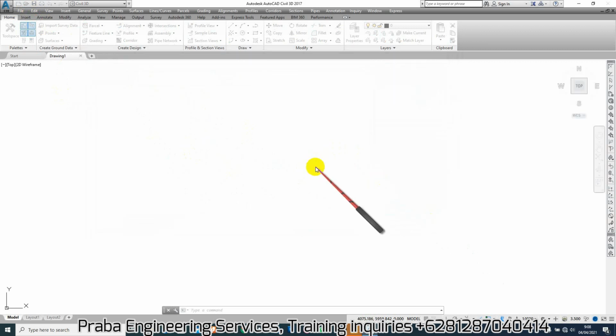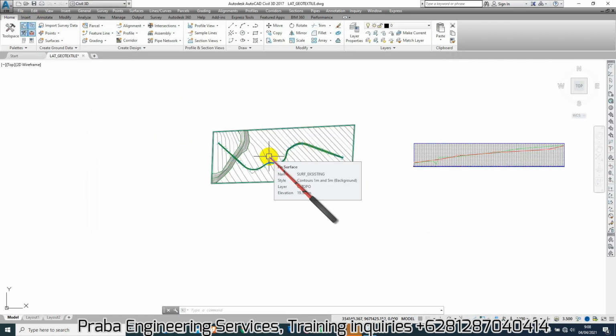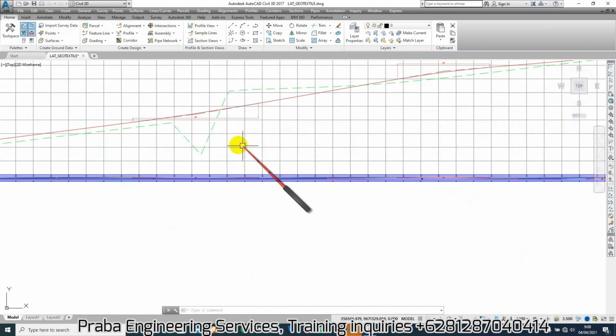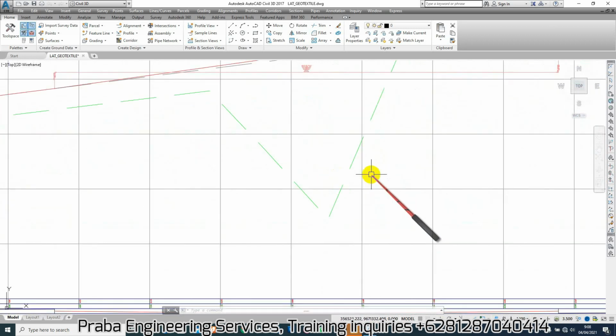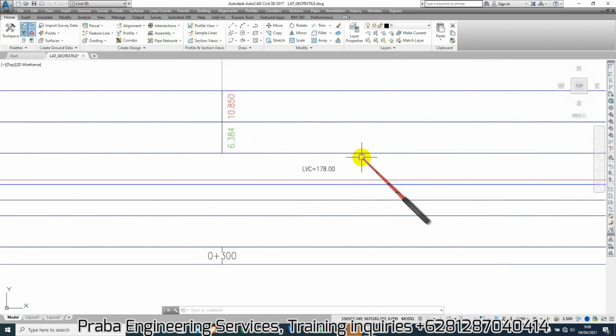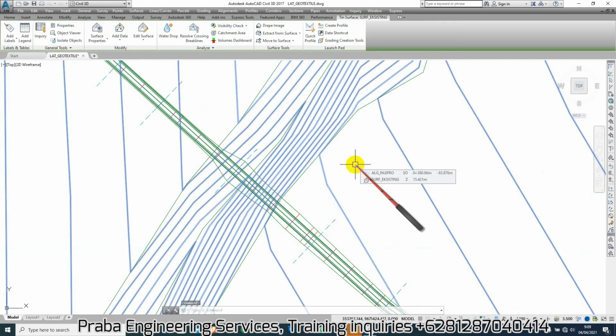This is the MC0, or what we call the original existing ground. When we see the long profile, in here there is some location that is lower than the others. In here, around the station 0 plus 300. This is the original ground level. Then the next step, we ask the survey to get data location to make sure the precise location of the Selected area or location that we want to build.